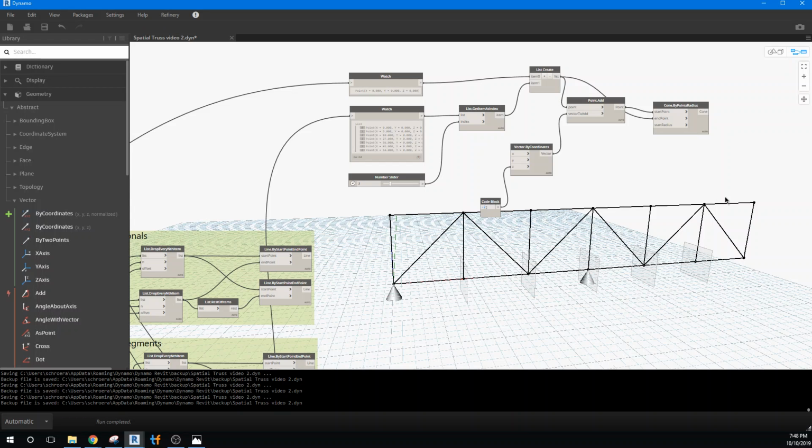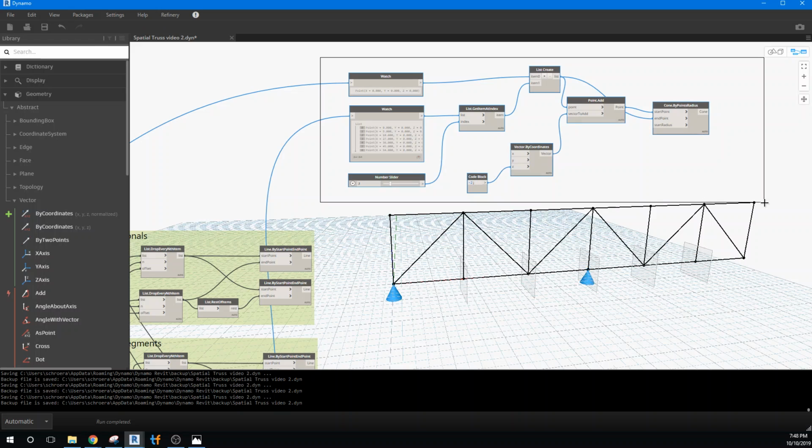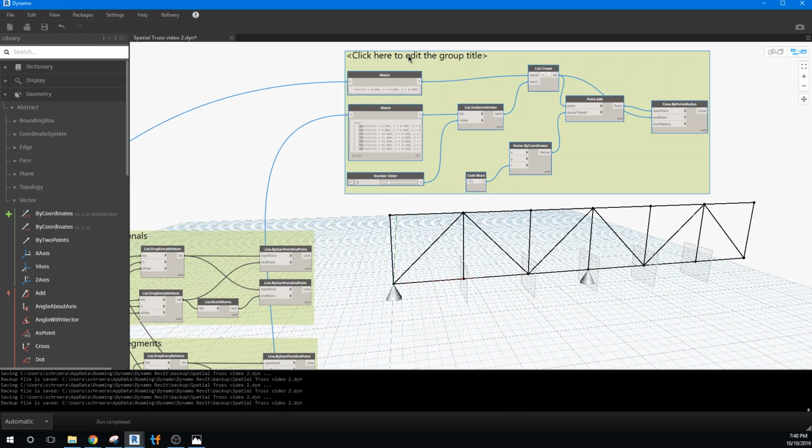And the next thing we want to do is really just duplicate the same concept, but by applying loads to the top. So what I'm going to do right away is grab this whole group, make a group out of it, and we'll call that group supports, truss support. Okay, so the next thing we need to look at then will be the loads that we're applying, and we'll do that in the next clip.